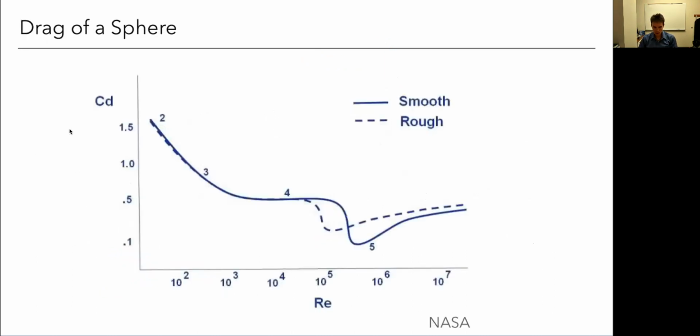Okay, so just briefly want to remind you about, this is the same idea we're just discussing earlier. I'm sure you've all seen this, the drag of a sphere, and often we hear these analogies or explanations of this behavior, like say for a golf ball, why does it have a dimpled surface? Well, this figure helps explain it, as we've seen that a laminar boundary layer is going to separate pretty early, right? Whereas a turbulent boundary layer, because of that momentum near the surface, can extend further and delay separation. And so for a blunt body like a sphere, that means as I go from the laminar and then into turbulent, I can get this big drop in drag because of the profile drag.